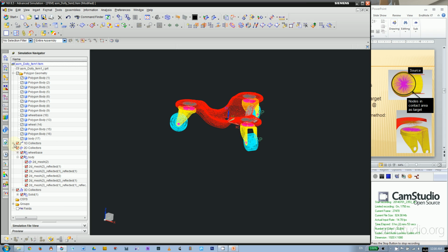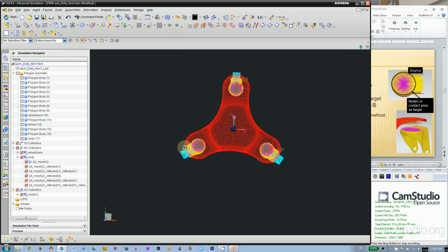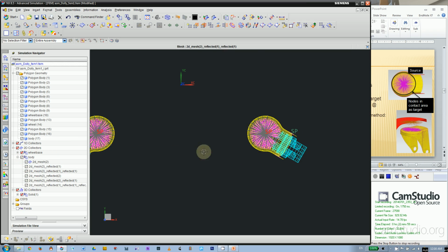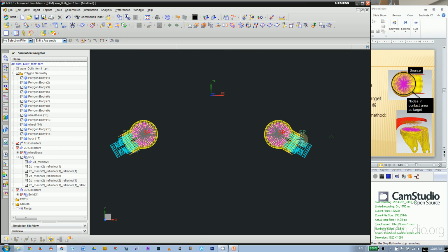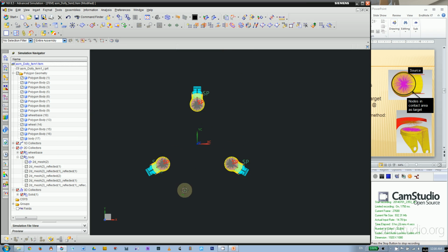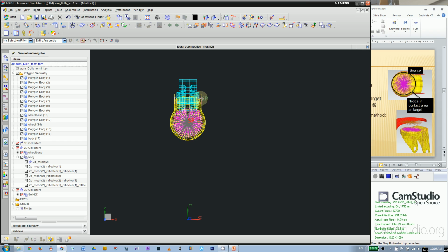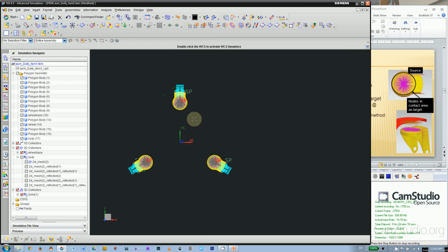But wait, take a look at the C-bush for the wheel axles here. Remember, for the wheel axle for the master copy, we assigned a stiffness that can make this bushing rotate only in the X rotation direction.